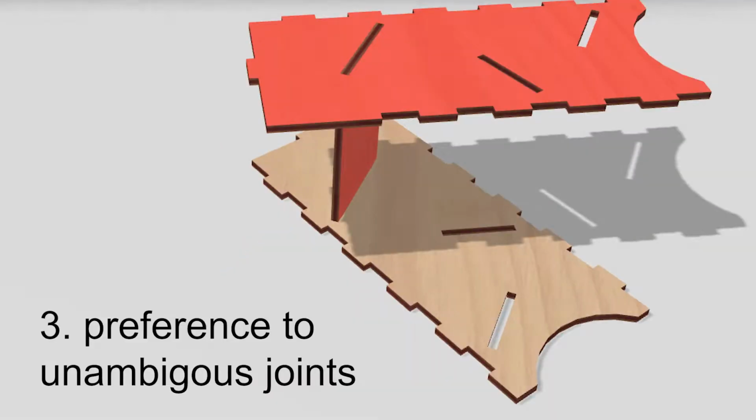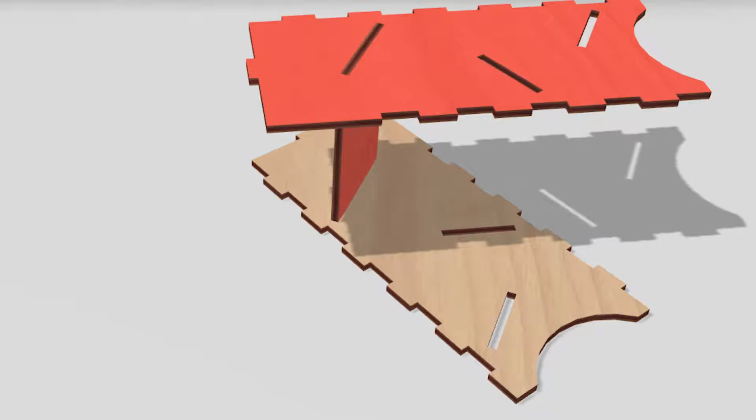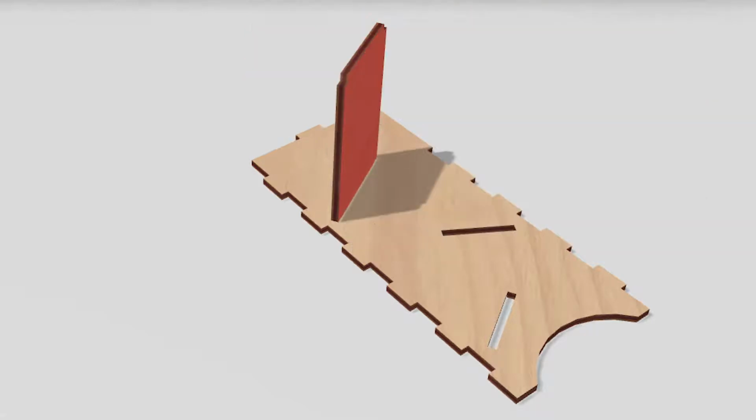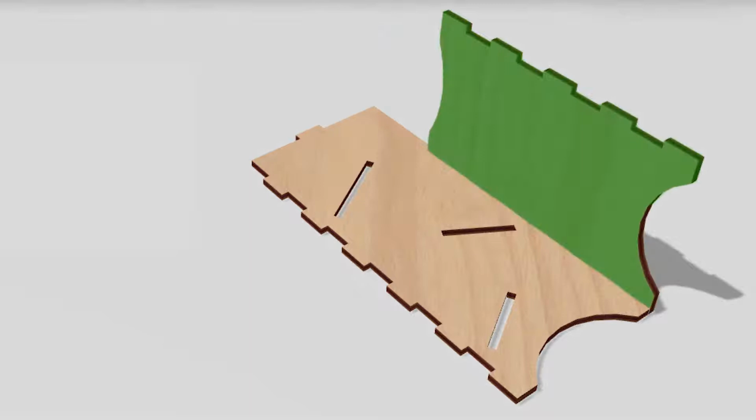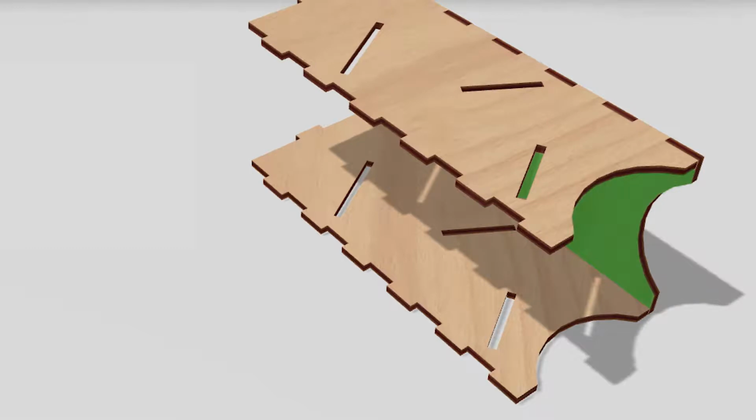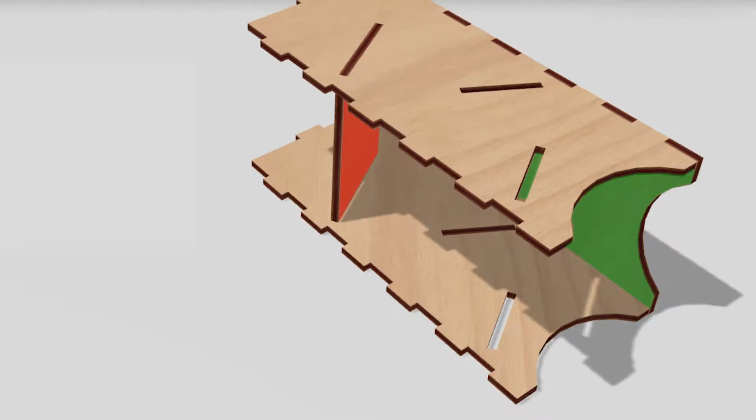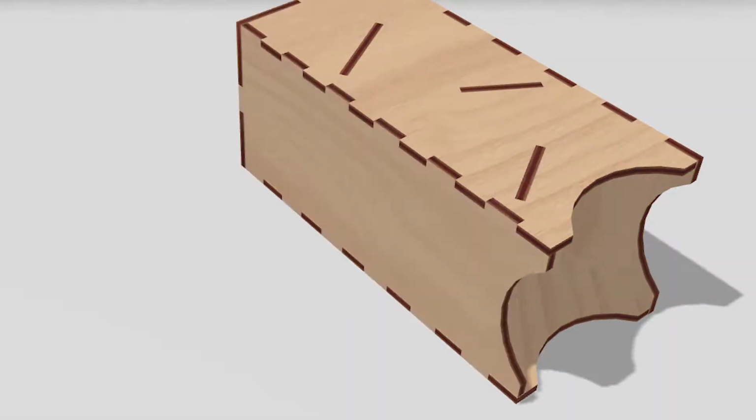3. There is a large number of ways to insert this plate into the model. The real problem is the plate autoAssembler inserted before this plate, which had 4 different matching joints in 16 orientations. autoAssembler prevents this from happening by preferring this candidate, which has only 1 other joint in 2 orientations. Assembling that plate first poses constraints to later on minimize plausible orientations of the joints on other plates.